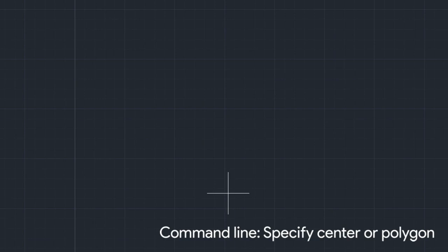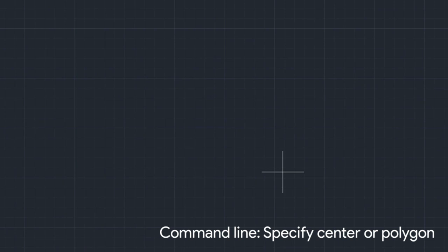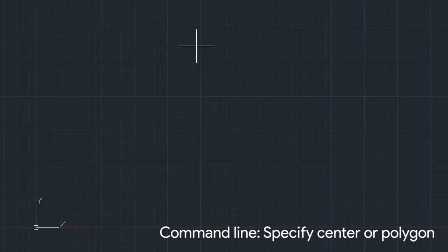So the number of sides, I specified it to be 5. After I pressed enter, you're asked to specify the center of the polygon. And again, you can specify the center of a polygon by either inputting the coordinates or just clicking wherever. So, okay, let's just click.